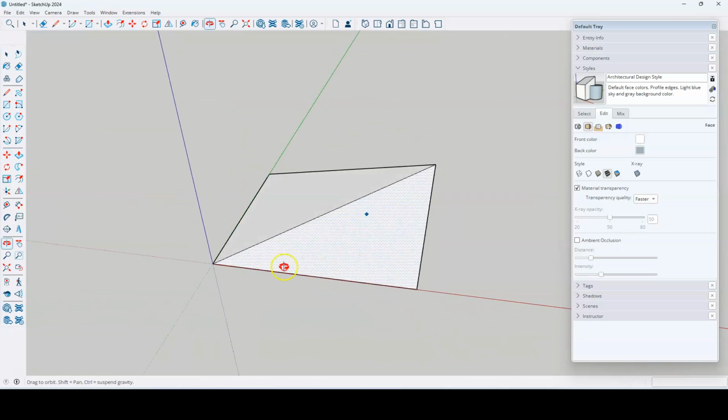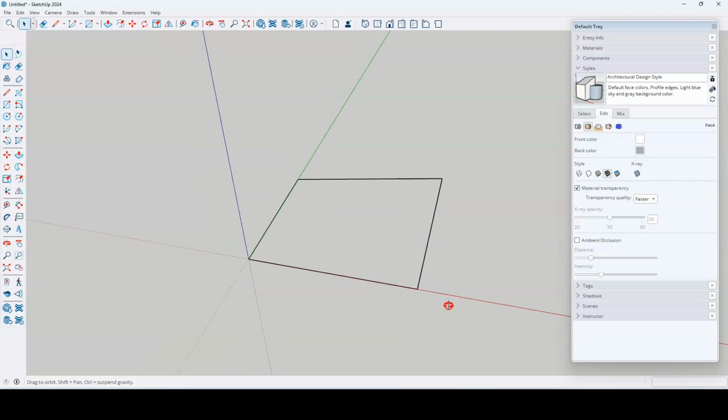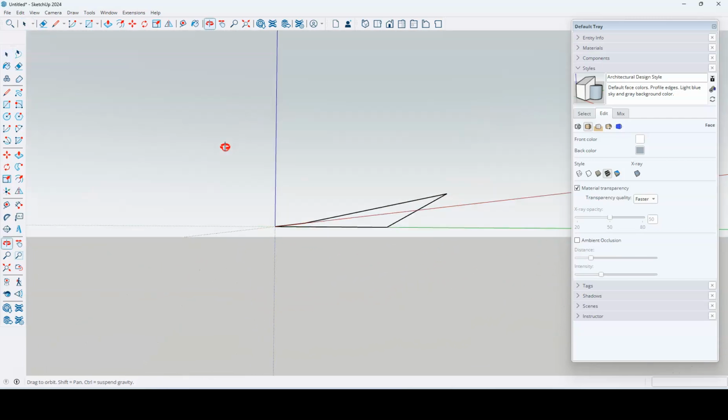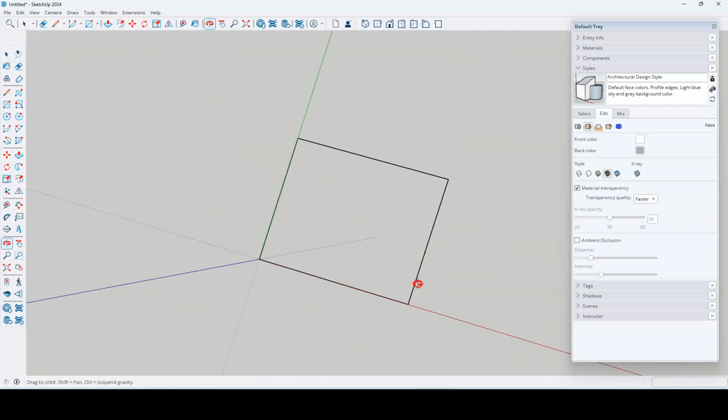This will kind of create a little bit weird surface for me, but let's say that that surface didn't happen for me. Now, obviously, you all saw me move that endpoint, but let's say you're looking at it kind of like this, and you're like, hey, why is this not filling for me? This looks like a rectangle to me. We can kind of check to make sure that our endpoints are indeed all on the same plane.